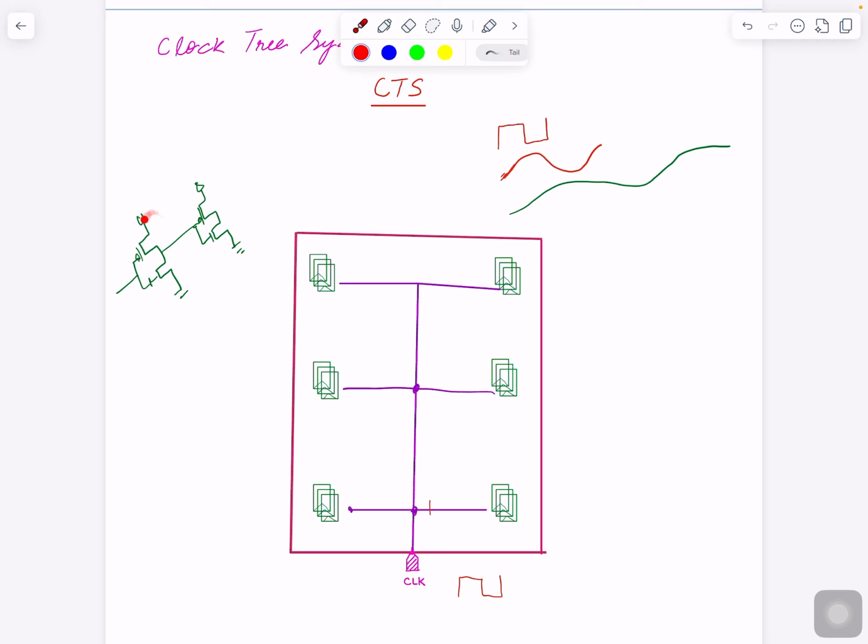I mean, inverter has full capability: if the signal becomes weak, this is where our CMOS helps us. CMOS is really good at pulling a logic back to VDD or VSS. And so it is very good to remove that noise, to remove this situation. It's kind of a repeater. It repeats the input signal. It tries to recover that input signal.